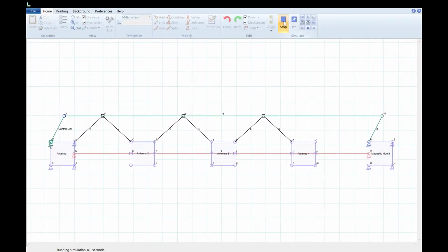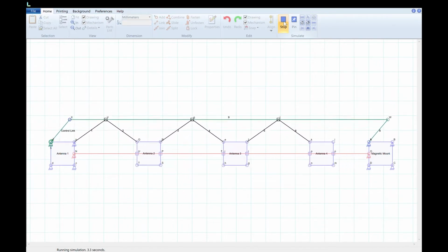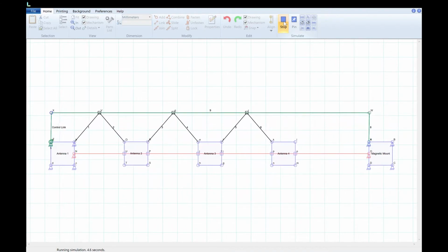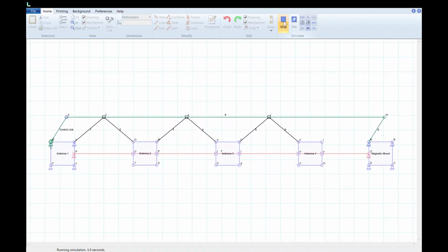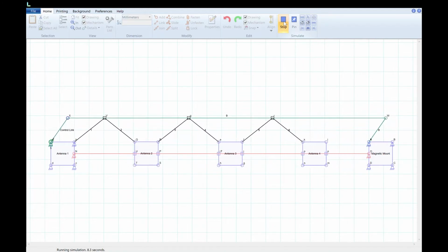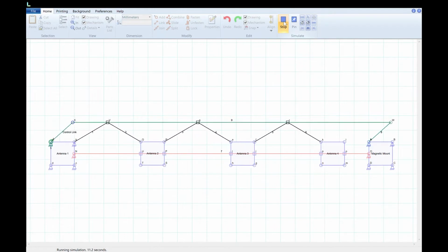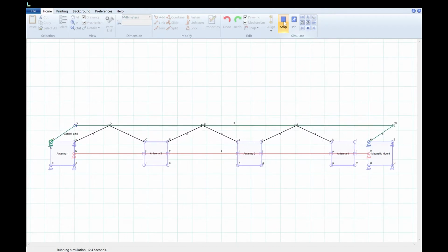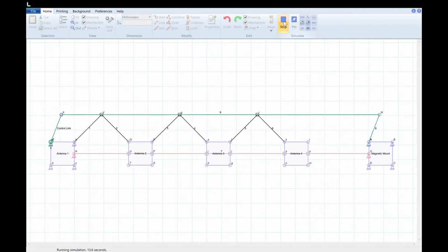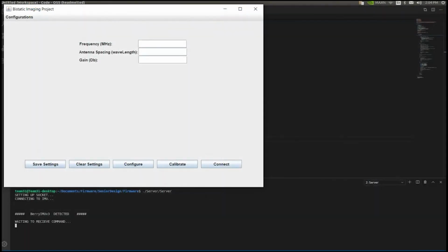It's made of three rolling carts that slide along a linear rail via an accordion connector. The accordion connector separates each antenna at an equal spacing as it oscillates. The spacing between the first and last antenna correlates with half a wavelength of the signal being picked up. Our design was built keeping in mind the range of frequencies of local TV towers across Tucson, ranging from 450 to 609 megahertz. Here, we are testing the data transfer between the ground station and our device.